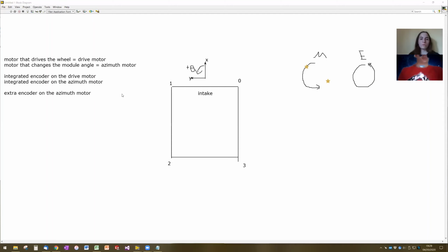That piece of information is always going to get stored in volatile memory. So if you lose power to that computer, you lose memory of what rotation you're on. And effectively, you now forget what direction your wheel is pointing. So even though you've got that encoder, you no longer know exactly which direction the wheel is pointing.